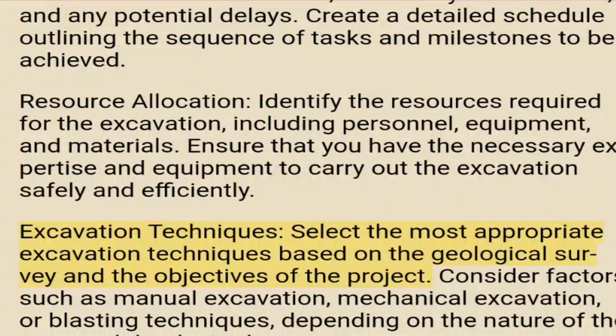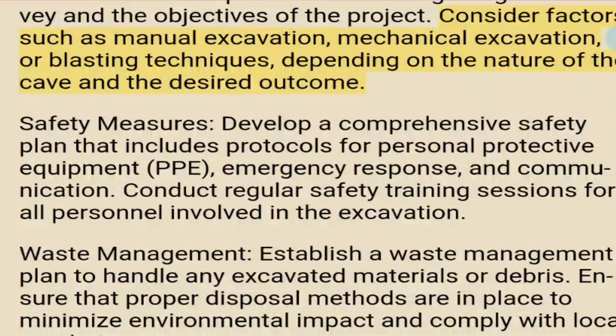Excavation techniques. Select the most appropriate excavation techniques based on the geological survey and the objectives of the project. Consider factors such as manual excavation, mechanical excavation, or blasting techniques, depending on the nature of the cave and the desired outcome. Safety measures. Develop a comprehensive safety plan that includes protocols for personal protective equipment (PPE), emergency response, and communication. Conduct regular safety training sessions for all personnel involved in the excavation. Waste management.